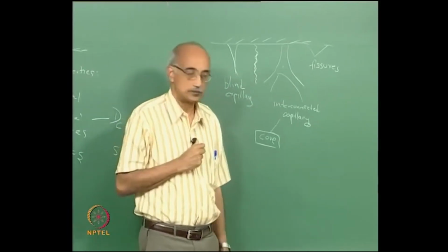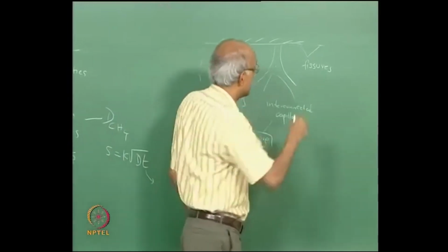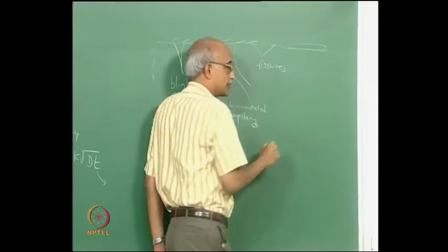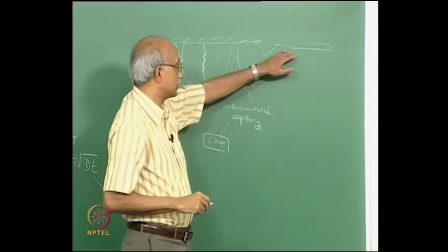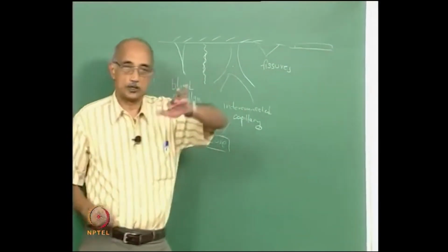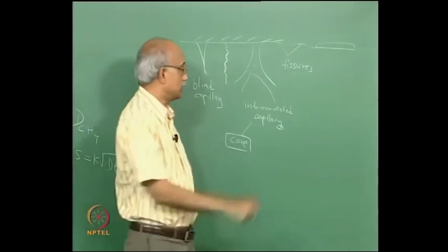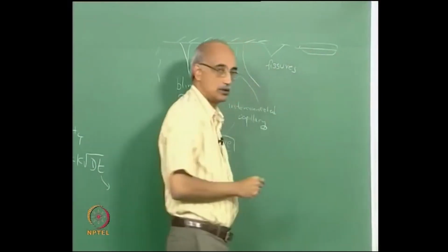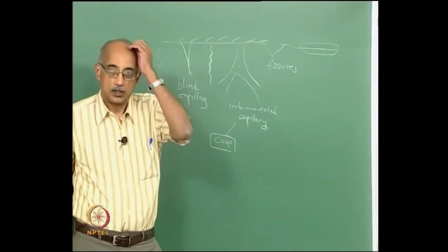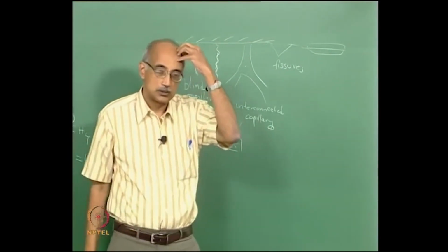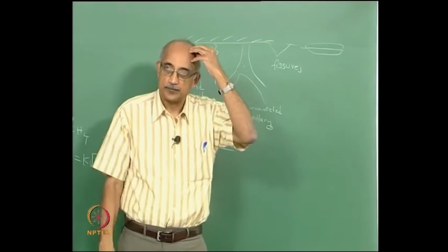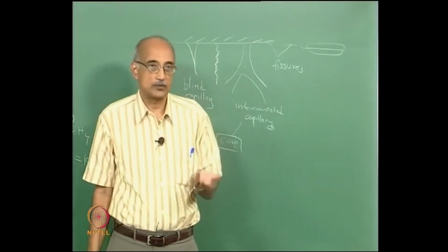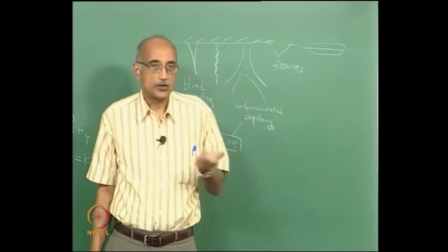And the other feature that you would see is if there is a coating on top of the material. Let's say that this is your surface and then you put down a coating on top of it. This coating or plating can actually penetrate into the subsurface also. It's very difficult to do any kind of surface treatment, whether it's painting or coating or plating or passivation, anodization.